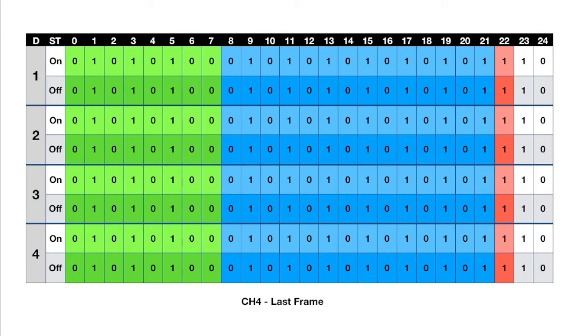So in this case, this arrangement of 1, 1 creates a 0 if we XOR them, but it looks like that they also flag the end of the transmission as a whole. So the end of the block. So whereas the bit 24 flags the end of the frame, bit 22 and 23, being both 1s, will flag an overall end to the block.